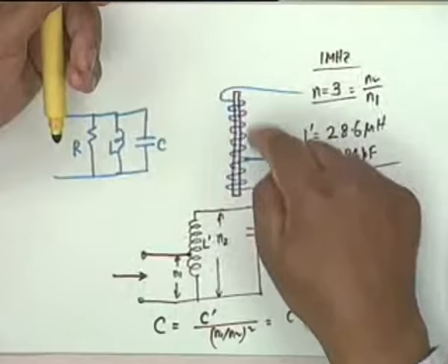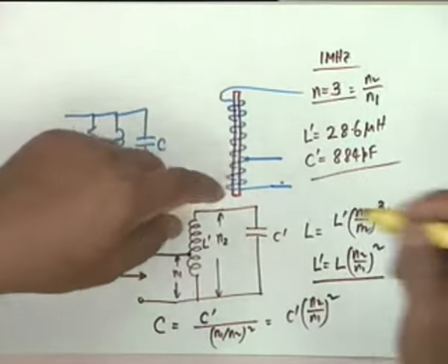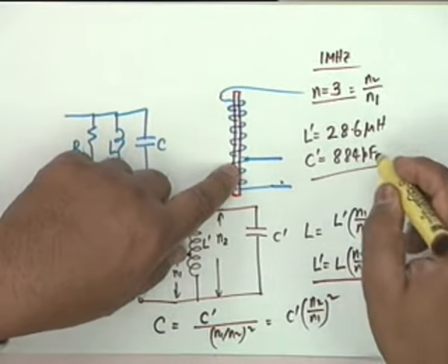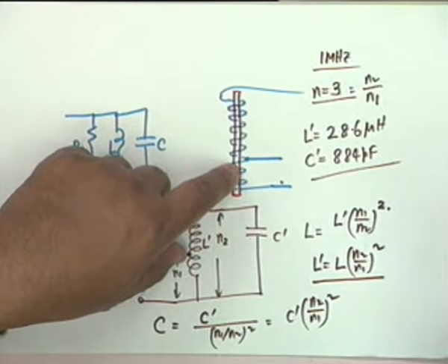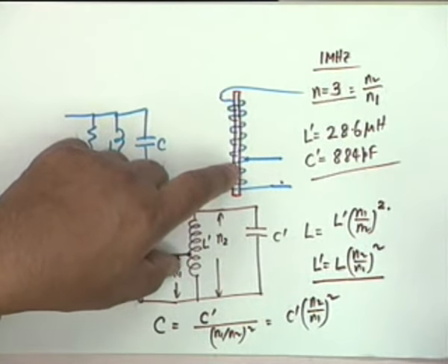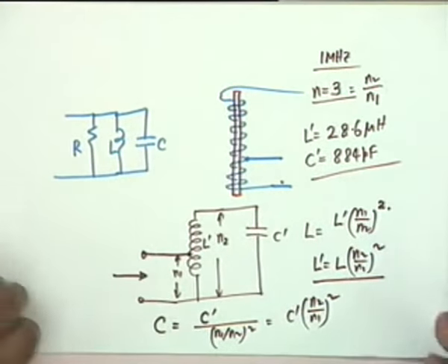One would be perfectly comfortable if it's a fixed frequency, 1 megahertz. I don't want all this mess. I want a fixed capacitance, and therefore an auto transformer there helps. You can slightly change the tap to make this a standard value which is available in the laboratory. Okay. For example, 792 pF, if I remember, that's a standard value. Some standard value that is available in the lab. So, an auto transformer is used.